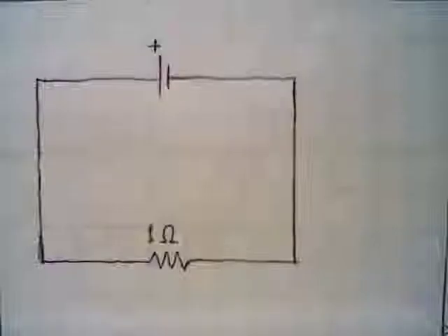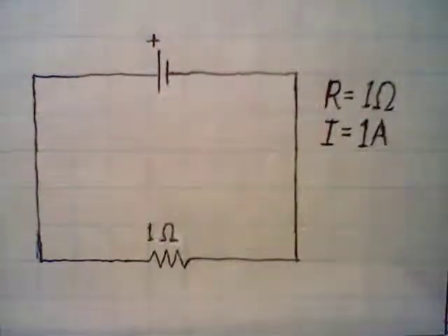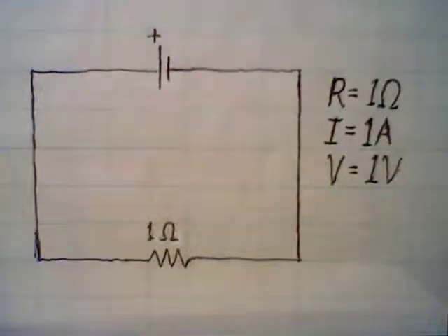The unit for electrical current is the ampere, often shortened as the amp. This is the rate of how many electrons pass through a conductor per given time. Now, in equations, you'd often see the ampere as a capital letter I. According to what's called Ohm's law, voltage, resistance, and current all relate to each other. The voltage is the product of the current times the resistance. An electrical conductor with a resistance of 1 ohm and a current of 1 ampere has a voltage of 1 volt.